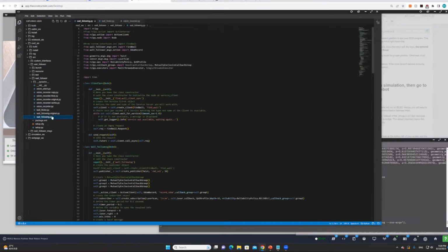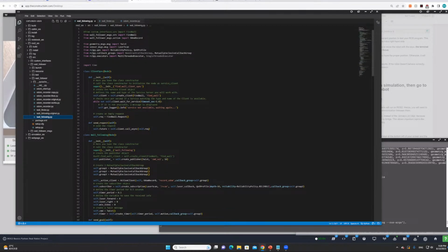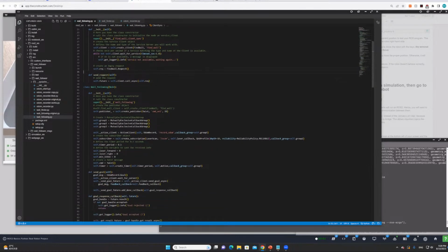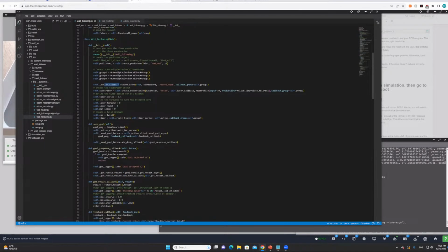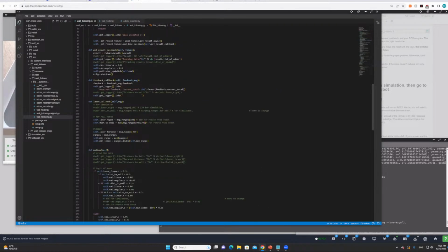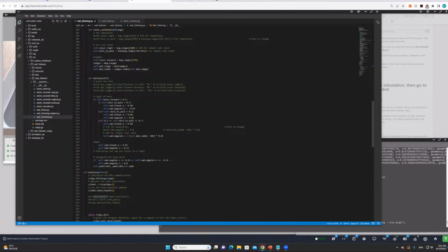And this is all following. When the action server and the service server are turned on, they are calling out first the wall find by sending a request, right? And then after that, I made another class for odom finding. So when this started, they create a client, and then this client is calling the action server by the method below. And then at the same time, they do the wall following motion like this, as you showed in the video.